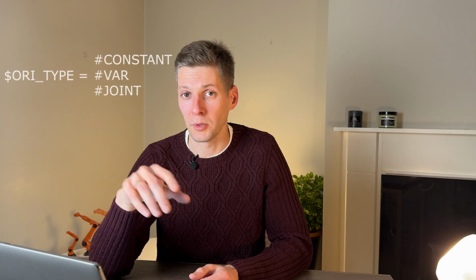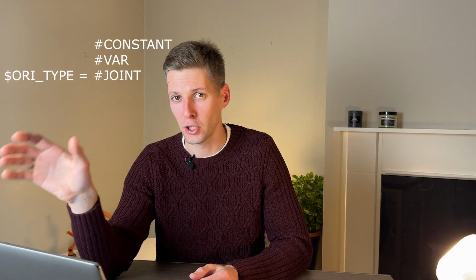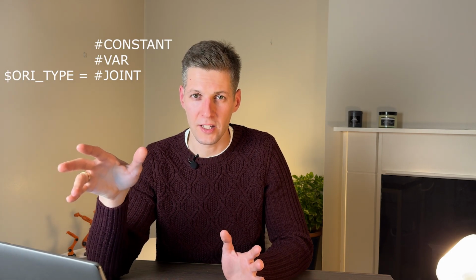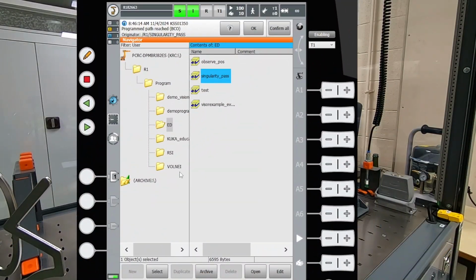Another way is to use the Wrist PTP feature. This feature is about changing the robot orientation during the linear motions. So if we apply the joint orientation, it is almost the same as what we did with the variable, like a usual case. During the linear motions, a robot will change the tool orientation continuously, but not uniformly. So it's a very crucial limitation in some applications where the robot has to maintain the tool orientation exactly as desired, so it's not a feature to use for this application. Okay, let's select our program again.